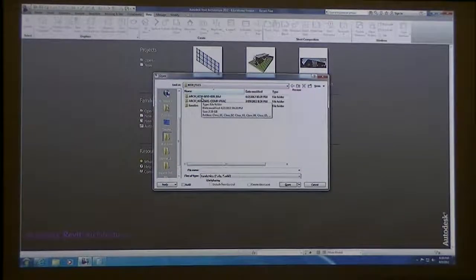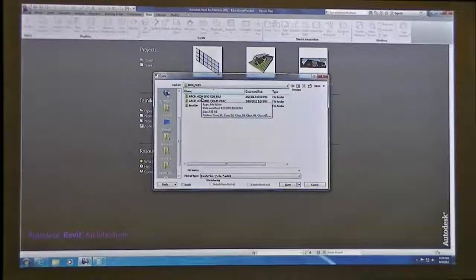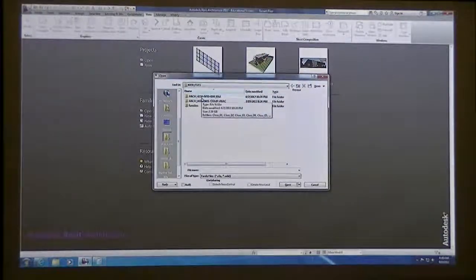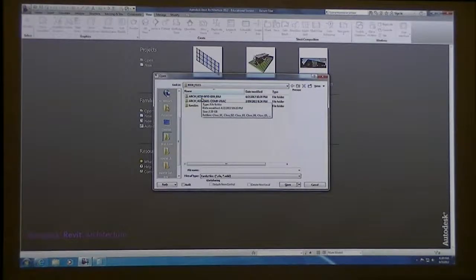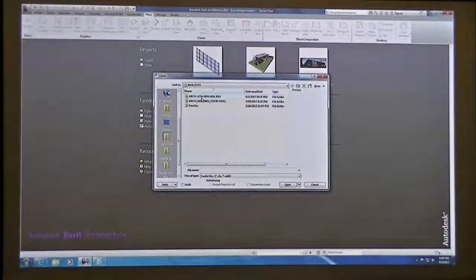A lot of times too, like I mentioned with the manufacturers, they're now getting involved, or have been involved, so they're developing their parts and pieces. I would probably look at Autodesk Seek, and then maybe even try to find a manufacturer who actually does a spider clip system, because they might actually have their parts done in Revit. And then your last resort would be Revit City, where you can get the generic model that has no parameters in it.